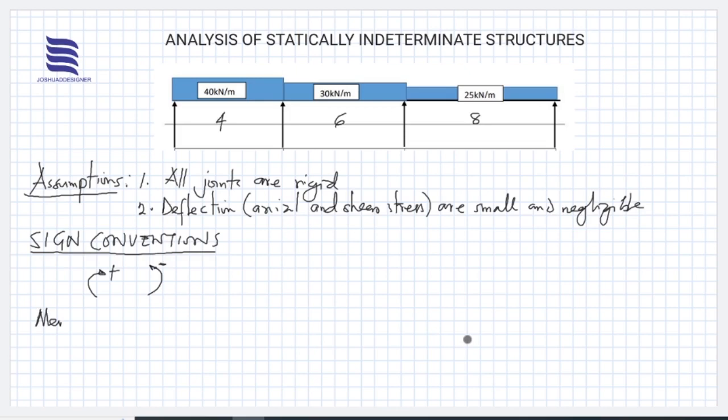So the member stiffness is denoted as K, right? To obtain this, you need to pay attention to the end condition of your span. The assumption says that all our joints are rigid and unmovable, such that they are fixed. But we would want to pay attention to our end support, because most times it defines what expression we give to our stiffness in application. So we just want to paint one or two things, and we'll give explanation to them simply in this tutorial.